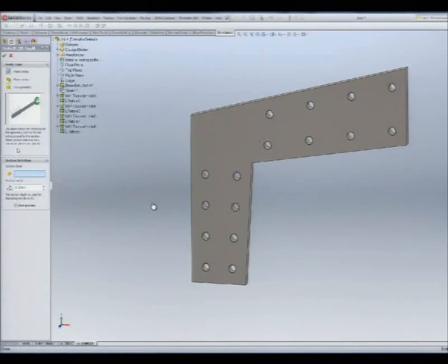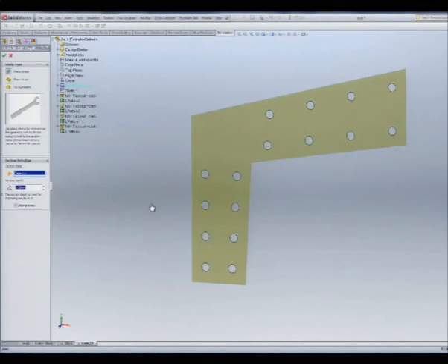Plane strain is useful for what? For example, for tunnels or for pipes, where plane strain means that the deformation in the axial direction is zero. And finally, the axisymmetric I will explain in another slide. So in plane stress, I have to choose the plane to take into account and the width of the plate.